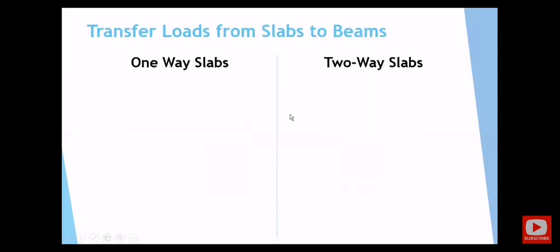So how to transfer loads from slabs to beams? If you want to design a beam, you need to find the load on this beam, and then make some structural analysis to find the bending moment and shear forces. Then you go for the design steps. So the first thing is to find the loads. You cannot find the bending moment and shear forces without finding the load.